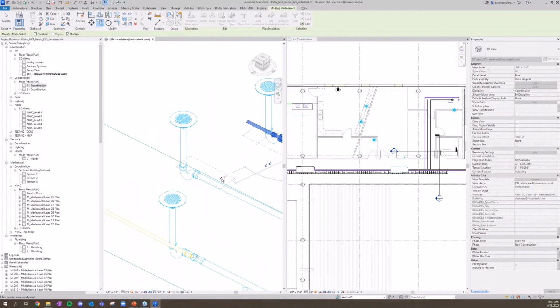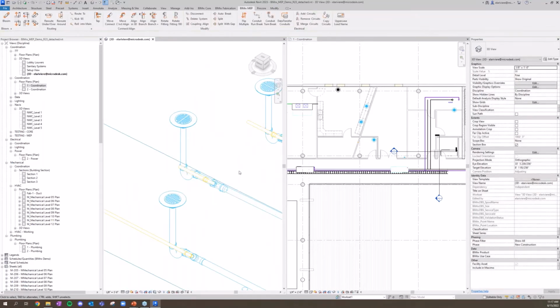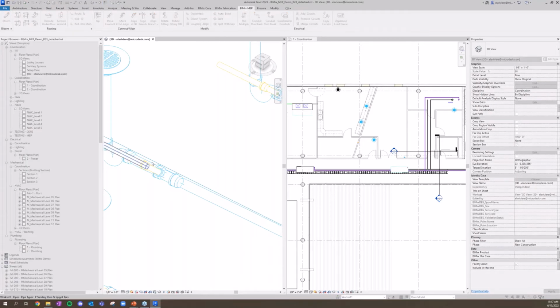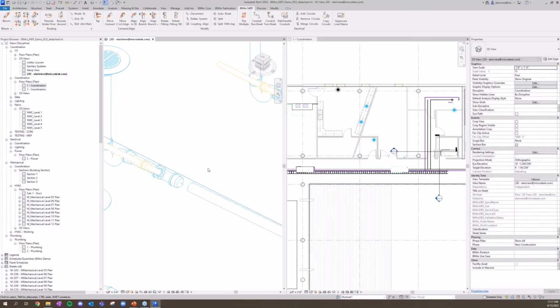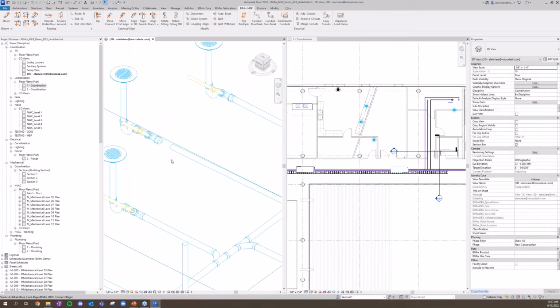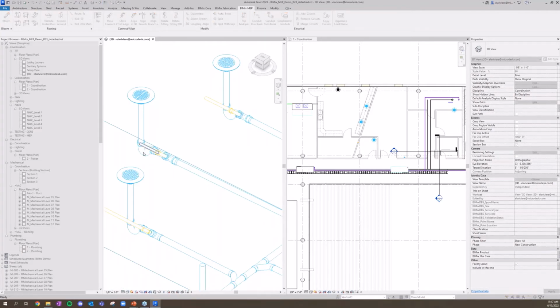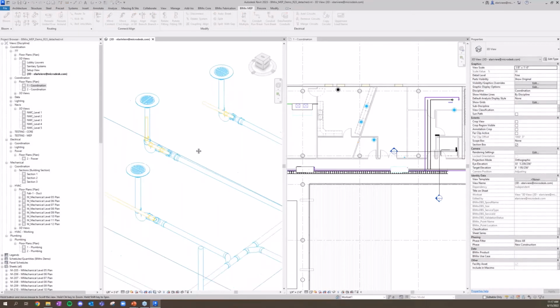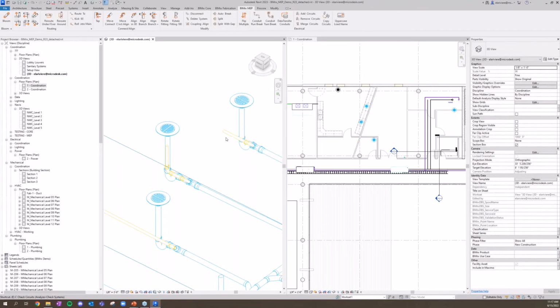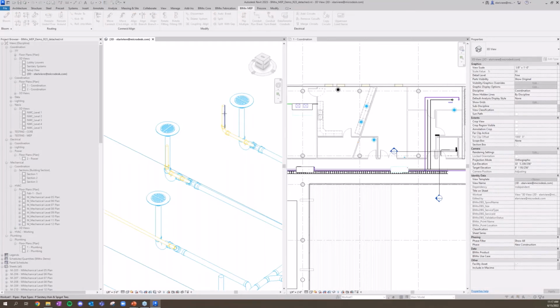I can grab that little vent section, bring that over and get it close, because I'm going to let BIMrx do the final steps. Use something like split, because our split with gap does not place couplings. And then I can use move connect again to bring these elements back together. I can use move connect again to cause an extension. I can do an elbow up to start building out my vent system. I can do an elbow to the left. Elbow up, elbow left.